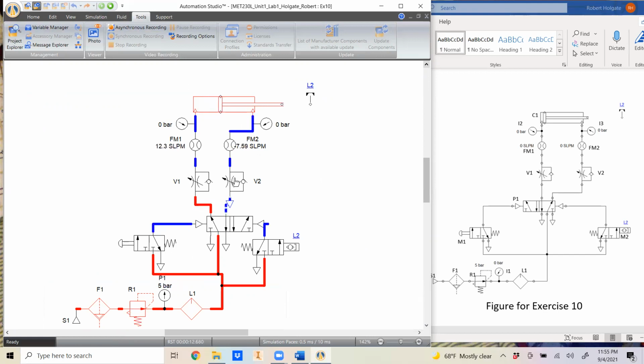Okay, I slowed everything down with these flow controls. Once it hits the reference point, bam, it sends the signal, an impulse on the right side because of the solenoid, and it sends a real quick impulse of air to the right, but that's enough to shift over the DCV. So we watch it again. Right when it hits, it's going to activate this 3-2 valve and let some air through. Just an impulse enough to shift this DCV back over and cause retraction.